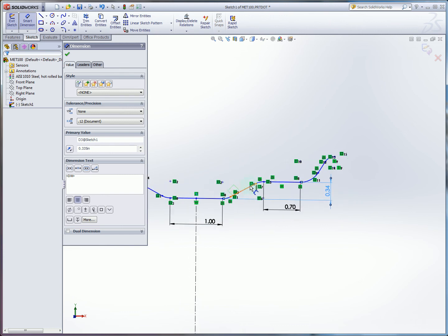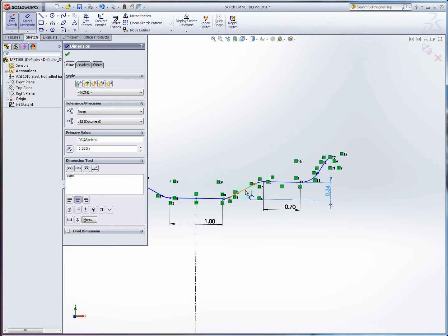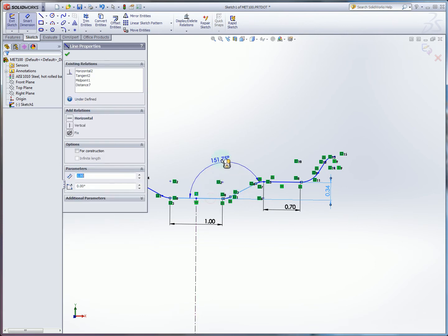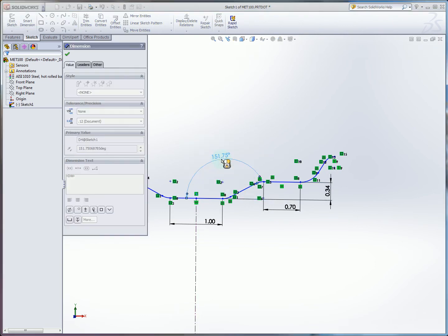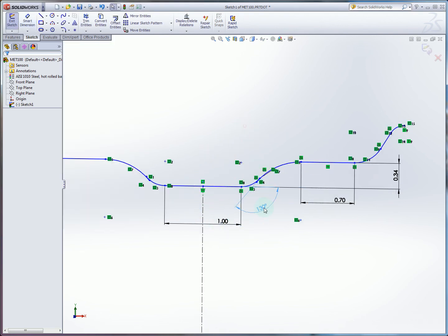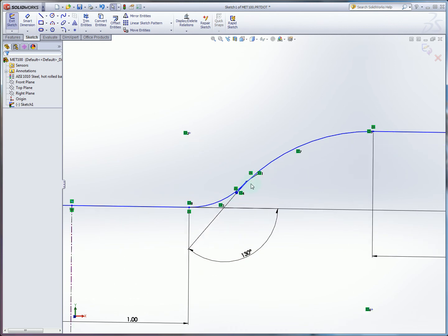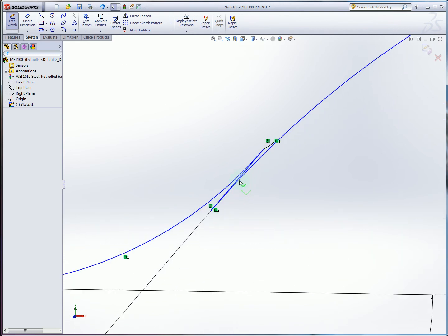At this point, we can see that our angle here is also similar to 130 degrees, so this might be a good time to click these 2 features and constrain the angle as well. Now, of course, this is sort of goofy in how it's been placed. We've got this vertical angle thing going on. You'll notice that when I added that constraint, we had this tangent solution that isn't really what we want physically. I'm going to zoom in on here so you can see what's going on.